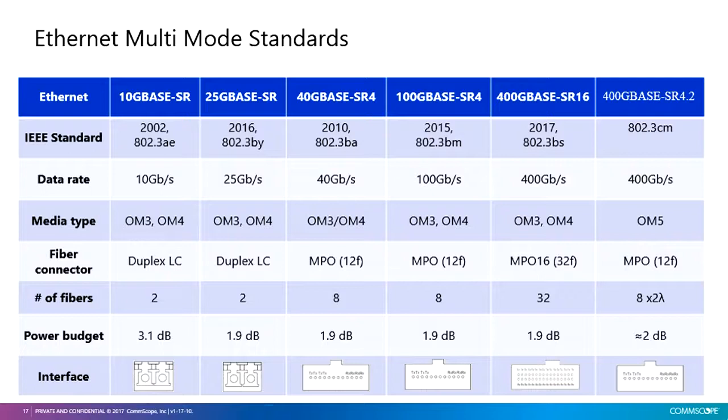So if you look at this power budget, I want you to remember this power budget value. If you remember 4 slides behind, we did a small calculation on the link loss budget, which is 3.35 dB. If you go with that loss, no application will work here, because each application requires a different power budget to work.